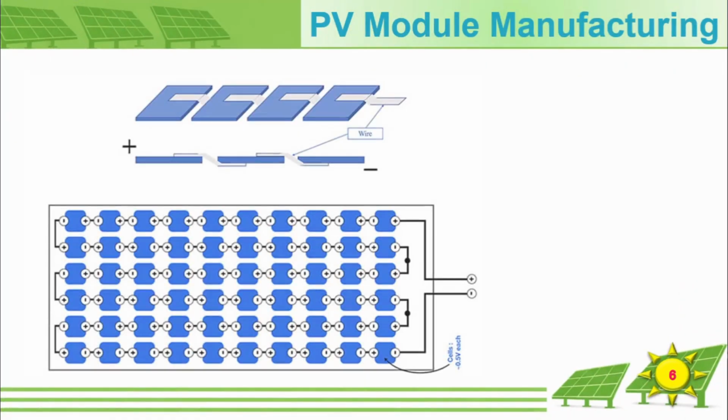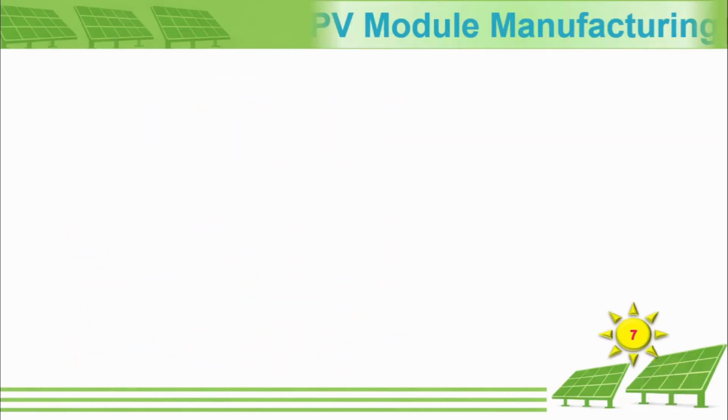As you saw in the video, each panel is made up of a specific number of solar cells. Each individual cell has its own specific current and voltage, and in fact, it functions as a PN junction. The voltage of each cell is usually only about half a volt, which is quite low for most applications. To achieve a much higher voltage and current in a single panel, these solar cells are connected together in series, just like what you saw in the video. You can see this clearly in the image provided here.